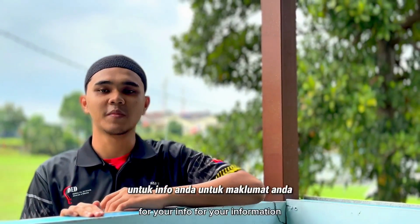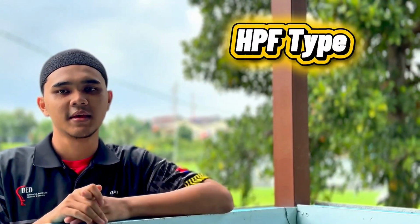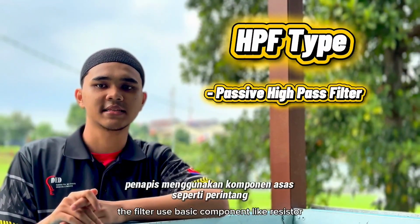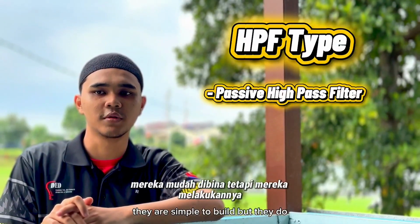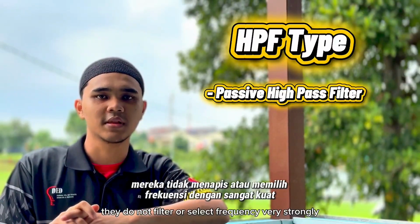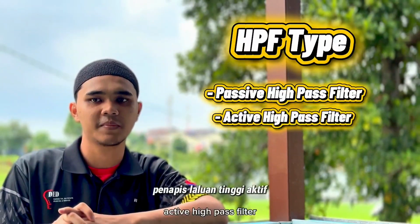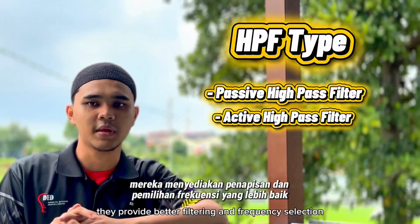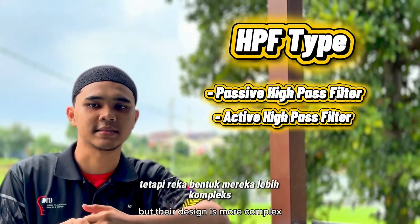For your information, there are 4 types of high pass filter. Firstly, the passive high pass filter. This filter uses basic components like resistors, capacitors, and inductors. They are simple to build, but they do not filter or select frequency very strongly. The second type of high pass filter is the active high pass filter. This filter uses an amplifier to boost the signal. They provide better filtering and frequency selection, but their design is more complex.